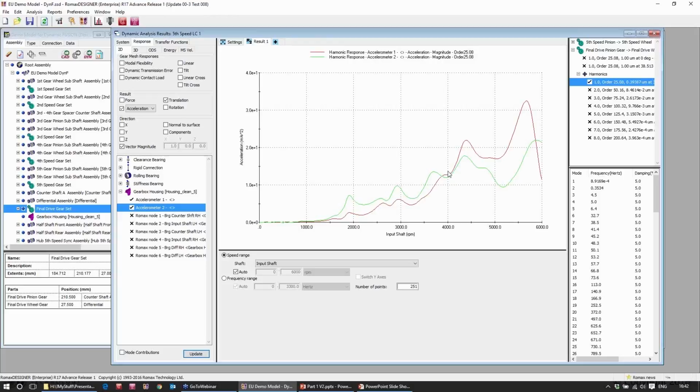So those are the kind of things we're going to be comparing with vibration targets. We could look at mount locations and that kind of thing as well. We can also export these vibration results and run them through an acoustic radiation simulation to predict the radiated noise, as you saw in the example that I showed from Ford earlier.